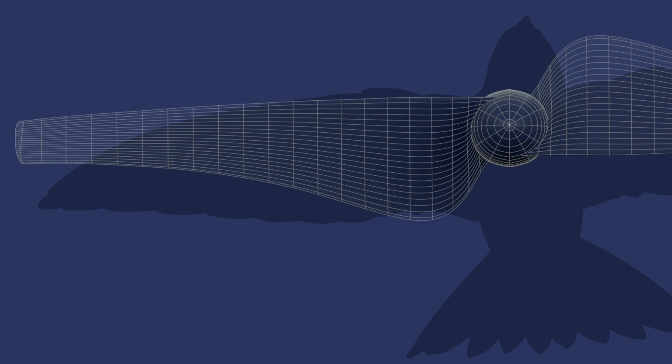The similarity between operating conditions seen by the Swift and the wind turbine implied a comparable Reynolds number experienced in both cases. This encouraged us to incorporate a back sweep to our blade as seen in the Swift. It was found that up to an 8 degrees backward sweep can increase the efficiency of the wind turbine. This increase in efficiency is due to the positive radial pressure gradient.